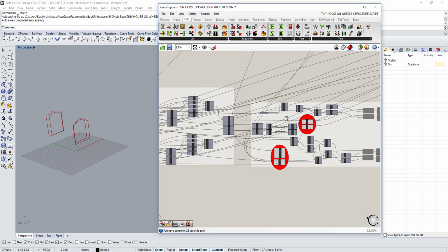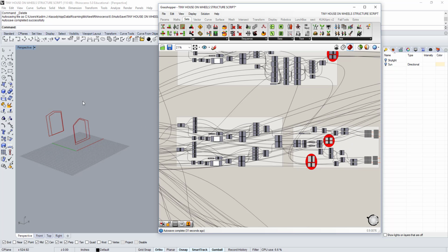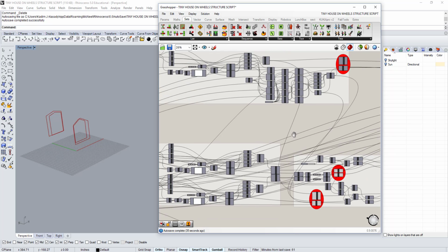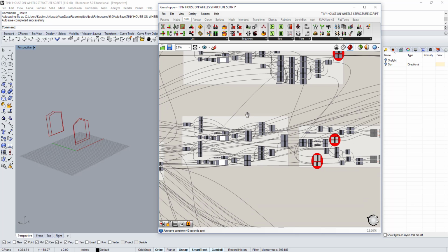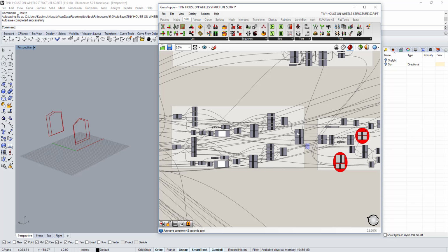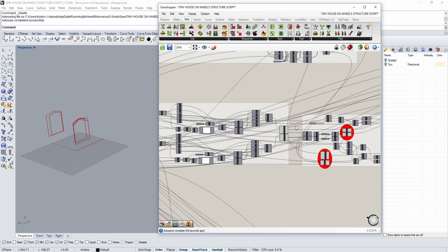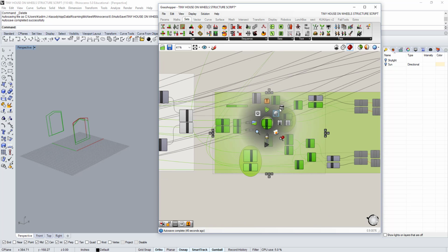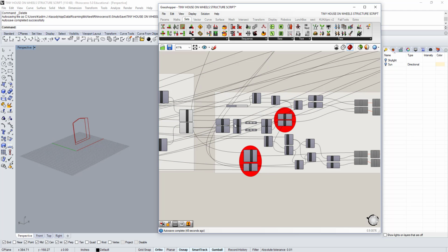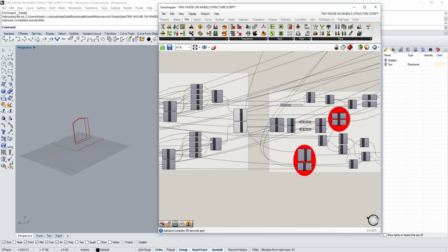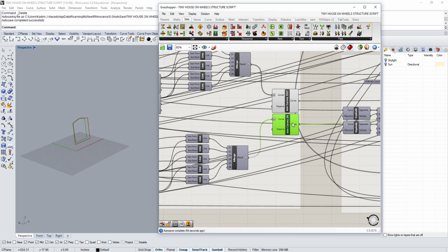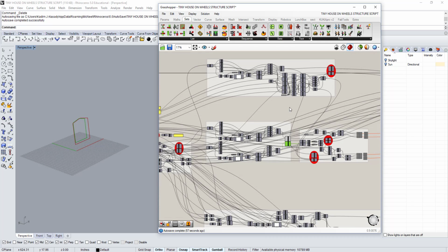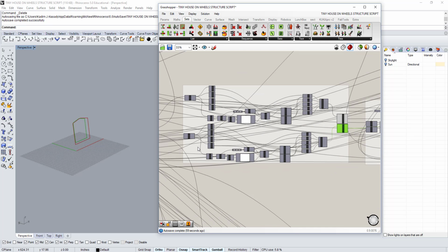So now what do we want to do? The other side of the dormer, this side, is essentially the same construction as the gable, but only utilizes a different slope. So really all we have to do is, let's turn on these 2 points. There they are. Let's turn off all these. So this is what moves the geometry of the dormer back to the back side, so then we can extrude it accordingly. All we have to do is really reconstruct these curves using all this geometry.